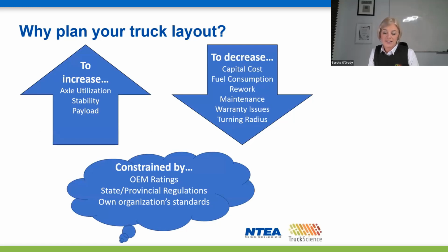As we know, truck design is all about competing priorities. In this graphic, the up and down arrows contain the things that manufacturers, upfitters, fleets, and end users care about. And the bubble at the bottom reminds us of what the chassis OEMs and governments need us to comply with. Performing weight, centre of gravity, and payload analysis before embarking on a truck build helps you to achieve more equal utilization of the axle capacities, better vehicle stability, and a higher maximum payload.